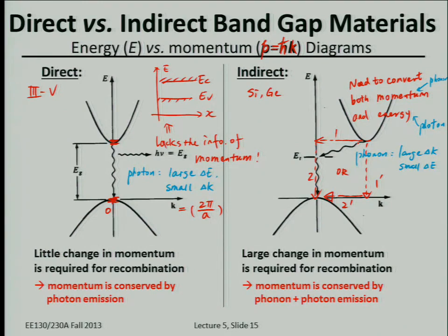If you grow a heterostructure, a thin layer of germanium on top of silicon, and then silicon on top of that, and germanium, basically very, very thin layers of semiconductor, you can make it more favorable for electrons to move in a 1-1-0 direction, or holes in a 1-0 direction, because you're changing the physical arrangement of the atoms on a nanoscale. Then the minimum of the electron energy can match in momentum space the minimum hole energy, and you can get direct recombination.